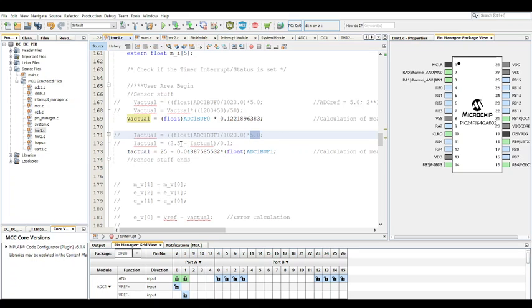And obviously, if you look at the data sheet of that current sensor, you notice a baseline value of 2.5, depending on how you connect it. It states that in the data sheet. The value is either going to be higher or lower. If you're working with a 3.3 volts microcontroller, I suggest you connect it in such a way that the value it reads is always going to be lower than 2.5 volts. Just make sure of that. Obviously you can connect it the other way, but I encourage not.